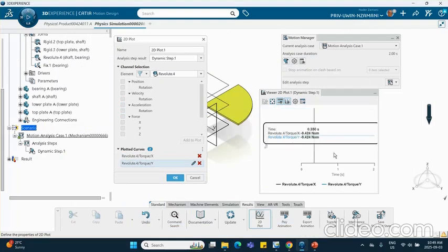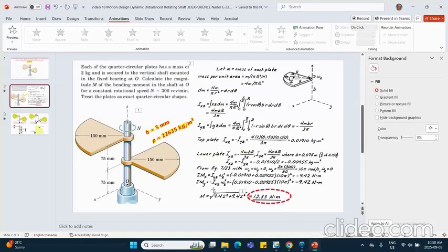Again, they're sitting on top of each other, 9.42. So the magnitude of the static moment down there is the square root of 9.42 squared plus 9.42 squared, which is 13.3. And we're getting exactly the same answer that the hand calculation in Meriam and Kraige gives you.